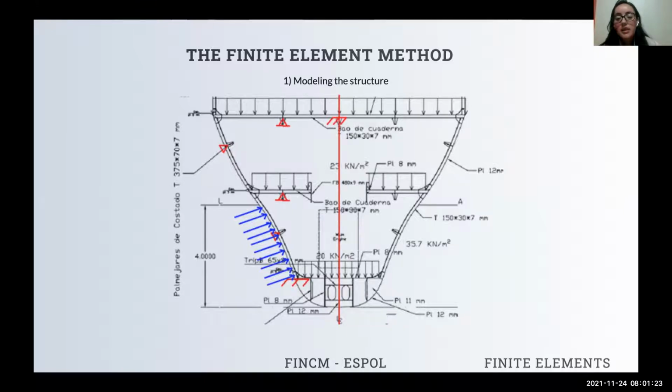The first is the double bottom is not going to be considered because it's a very rigid body. It is not a beam. The second, the structure is symmetrical, so we only consider the half. And the points that coincide with a certain line we consider as clamped. And finally, the longitudinal reinforcement we consider as a simple support.